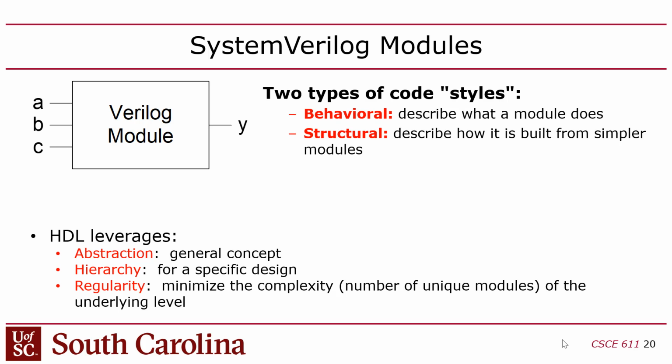And the other popular HDL is called VHDL. It has something called an entity. They're the same thing. Basically, this is the way that you decompose your design into things that you can design and then interconnect to form a design, right? So when you say logic element, it's equivalent to these idioms in the programming languages: module in Verilog and entity in VHDL.